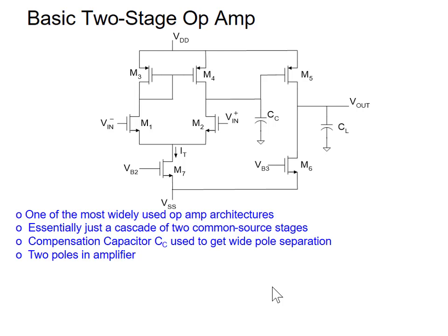There's 2 poles in this amplifier. Now, one thing this analysis missed, there's a feed-forward path through that compensation capacitor, and we will see that it introduces a right half plane 0. We can't pick up the zeros by this analysis. So we aren't quite perfect on this analysis. We will come back later and see how we can.